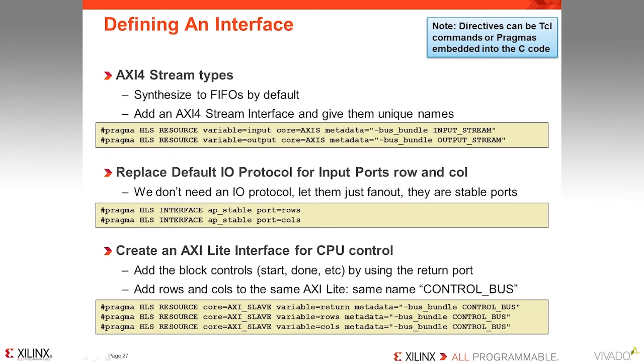Now, the other thing you'll notice, in the top right-hand corner there, is that directives can either be Tcl commands or they can be pragmas embedded into the C code. Okay? So in this example, I'm using pragmas that are embedded into the C code. But I'm just going to walk through them one by one.